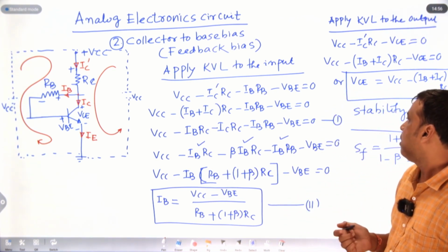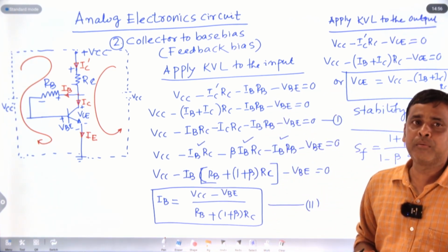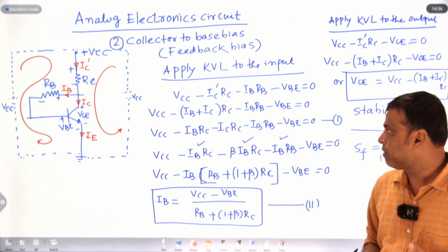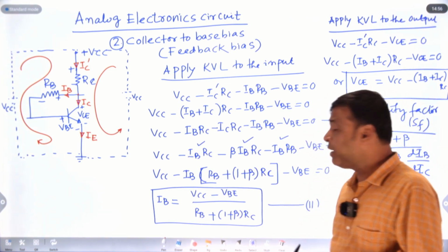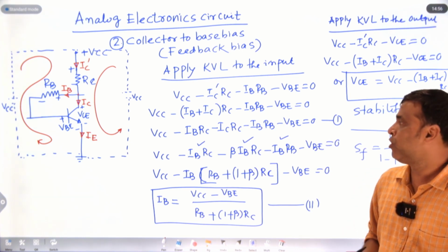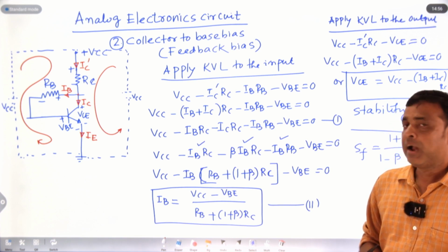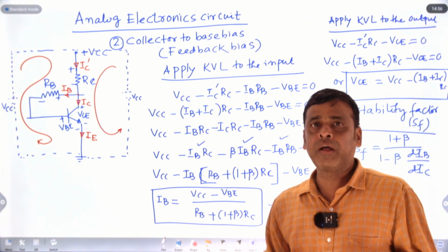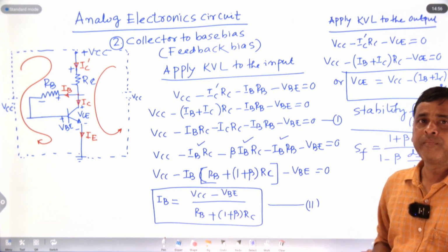If the transistor operates, heat is developed within the transistor, which means temperature increases. If the temperature increases, leakage current also increases. So every 10 degrees centigrade rise in temperature, ICO, the leakage current, doubles. At a matter of seconds the transistor will burn, and the process is called thermal runaway. The self-destruction of an unstabilized transistor is nothing but thermal runaway.